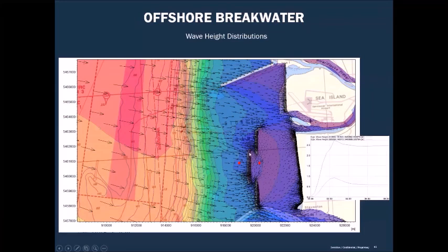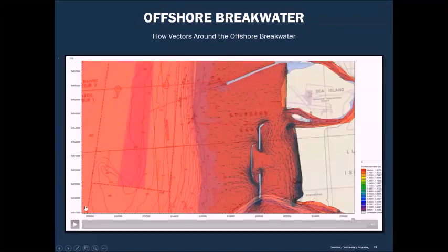So if I place a couple of breakwaters in front of the main dike, outside of the breakwater we have the 2.5 meter, and inside the breakwater, you can see the wave height is less, which means that we'll get less run-up and overtopping and less dike elevation.